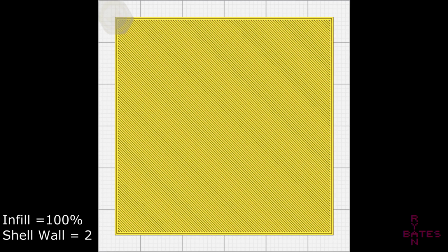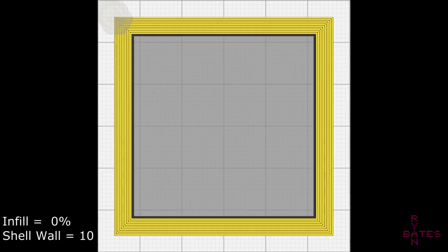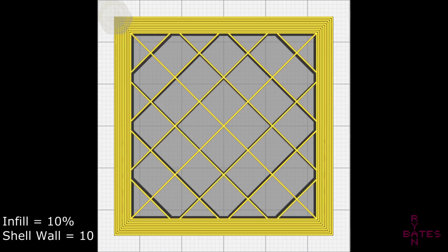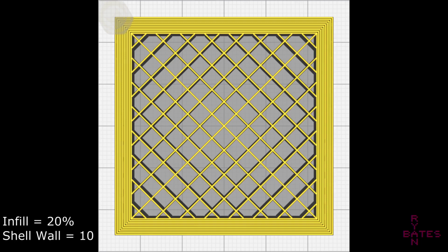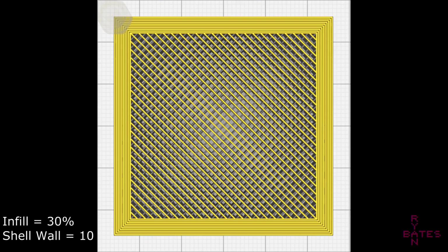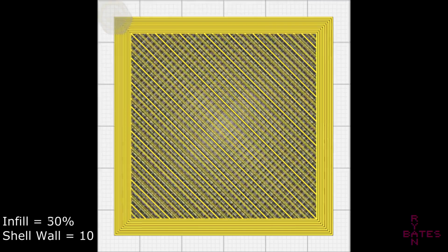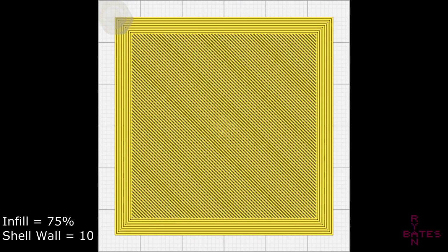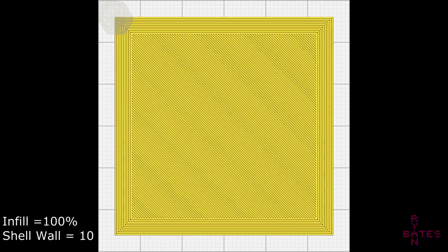you'll have to experiment with increasing the thickness of your part's shell along with infill. There's a magic ratio between both that will give you economical strength, assuming your part is sufficiently designed in the first place. Yet another option is adjusting the wall shell count, and that can also help you discover that magic ratio to strength and part density. So part density now being the infill along with the shell count.